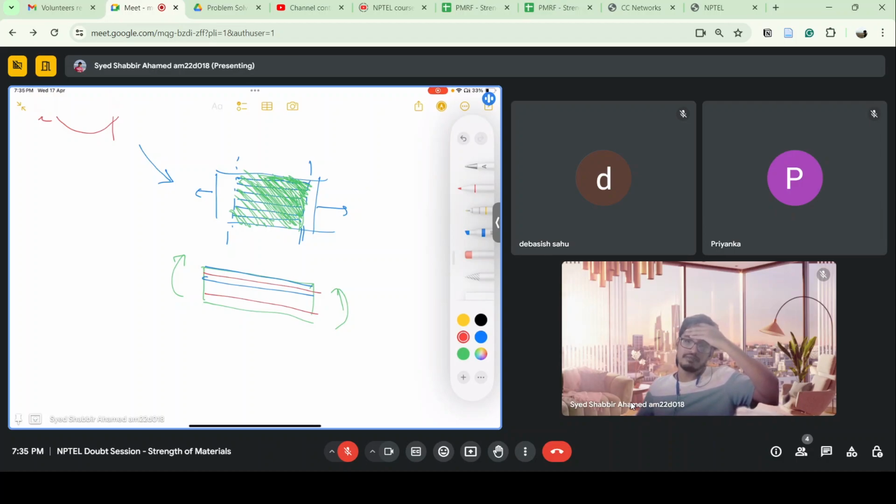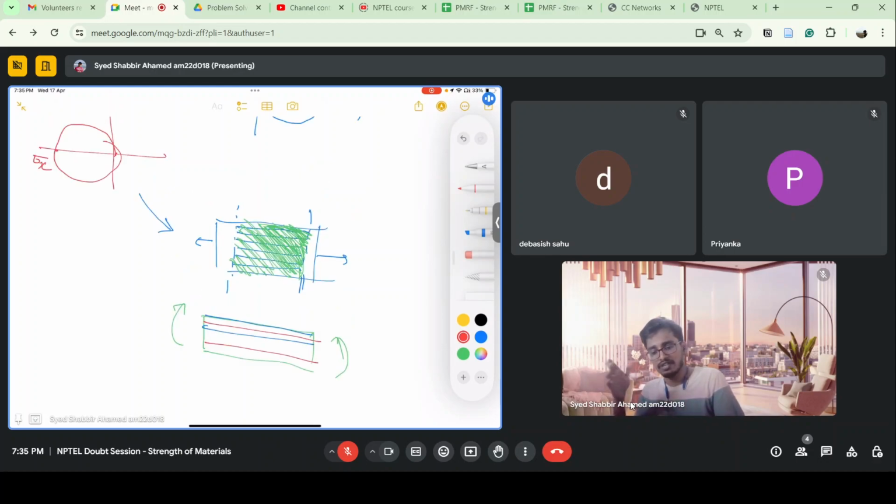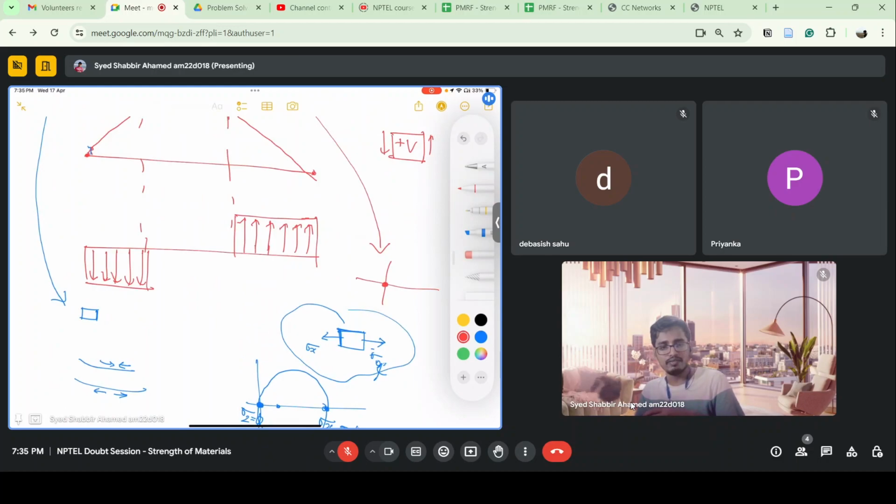But sometimes we do need the experiments, at least a little knowledge of experiments. We have the analytical things, like this Mohr circle, getting the bending moment diagram, everything. In order to do these analytical things, it is not humanly possible to take every detail. So we make assumptions. In Euler-Bernoulli beam theory, we ignore the shear stress because it is not very huge. But if I go to a beam which has very high depth, I cannot simply ignore it, because things will be different.